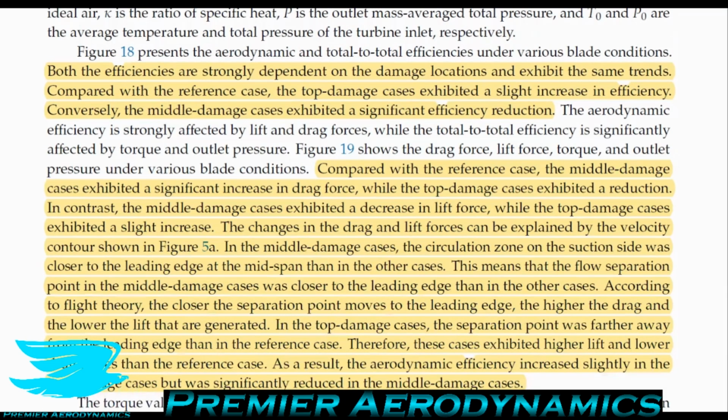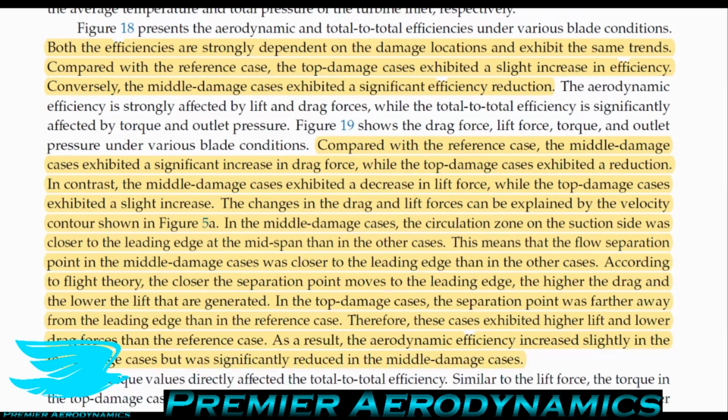So compared with the reference case, the middle damage cases exhibited a significant increase in drag force, while the tip damage cases exhibited a reduction in the drag force. On the other hand, the middle damage cases had a lower lift, whereas the tip damage cases had a higher lift. So overall, the tip damage cases were better, with drag reduction and lift increase. The changes in the drag and lift forces can be explained by the velocity contours, as we mentioned earlier, where they change the circulation around the blade.